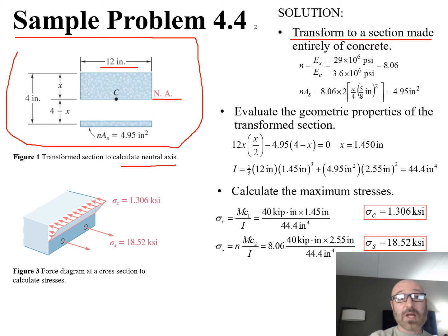And we have this shown below in figure 3 to calculate this. You can see there's a rebar right there, and a rebar right there. That's 6 inches between those. That's 3 inches there and 3 inches there. So 6 plus 3 plus 3 is 12. So that's how we're drawing this out and solving this problem. That's where we're getting the 12 inches from, and that's going to come into play in a little bit while we're calculating the area of the steel as well, because there are 2 rebar involved in this.